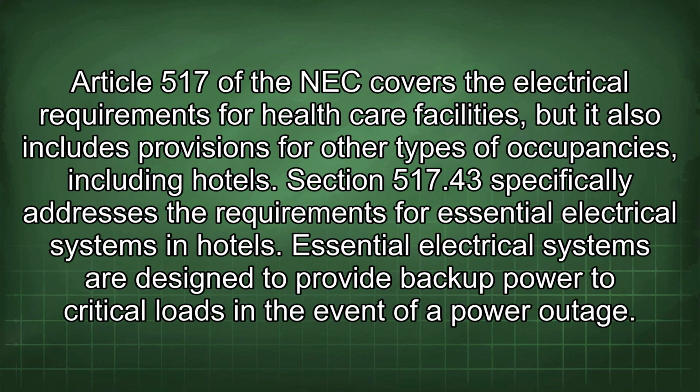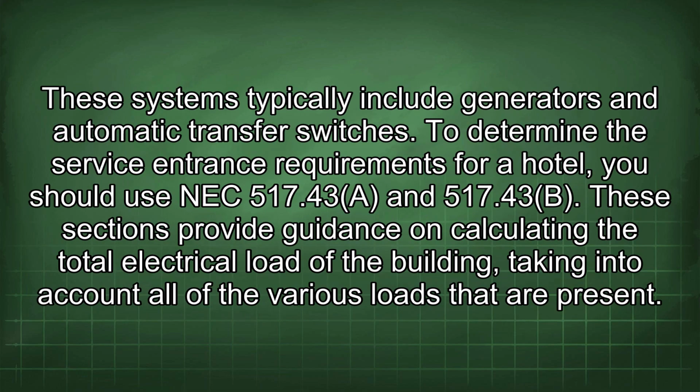Article 517 of the NEC covers the electrical requirements for healthcare facilities, but it also includes provisions for other types of occupancies, including hotels. Section 517.43 specifically addresses the requirements for essential electrical systems in hotels. Essential electrical systems are designed to provide backup power to critical loads in the event of a power outage. These systems typically include generators and automatic transfer switches.